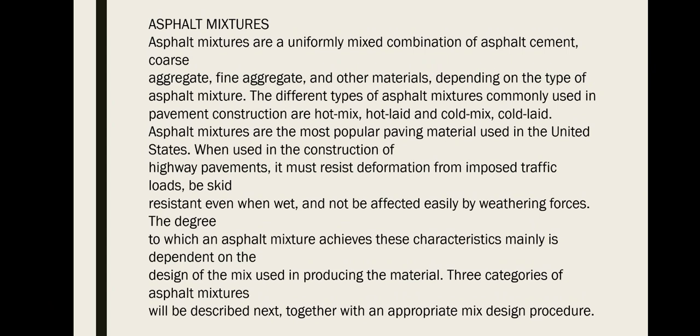Asphalt mixtures are uniformly mixed combinations of asphalt cement, coarse aggregate, fine aggregates, and other materials, depending on the type of asphalt mixture. The different types of asphalt mixture commonly used in pavement construction are hot mixed, hot laid, and cold mixed, cold laid. Asphalt mixtures are the most popular paving material used in the United States.